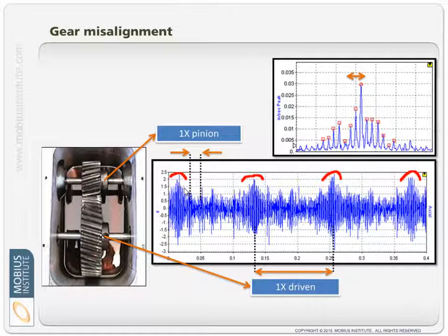That's when the lower speed gear goes through the mesh, how the forces change, and that's the higher speed gear. You can see the little pulsations in here. Now, the spectrum might show us this. These are sidebands in the spectrum. We didn't really explain that, but it's actually very helpful: we see all these little peaks, they're called sidebands. It means there's modulation. So if we do our spectrum analysis properly with enough resolution, we can see this. But we can see this for a lot of different reasons.